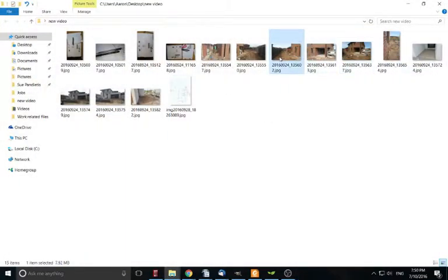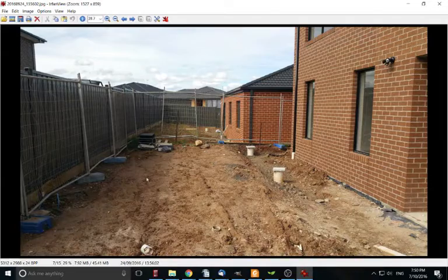and there's a better photo of the back. You can see there's this sort of grade of height here, and then it drops down quite fast. It's a bit hard to tell, but it's almost maybe 700 mil difference between about this level here and this sort of level there. So ideally we dig all this out almost as close to the fence as we can, put a retaining wall about a metre out from this fence, turn that into garden, paths down here, and maybe lawn area there, a central tree, maybe a bit of garden over on that side there.